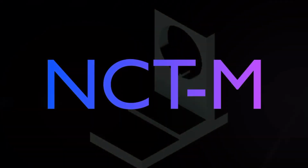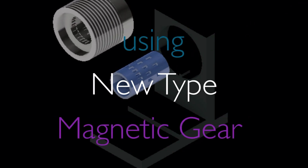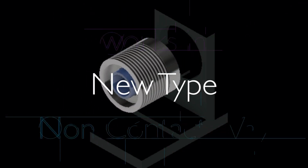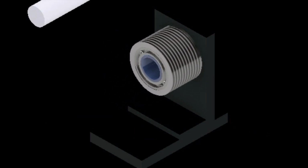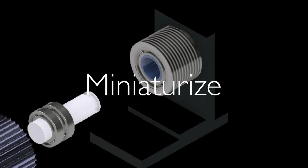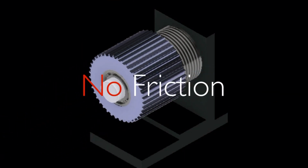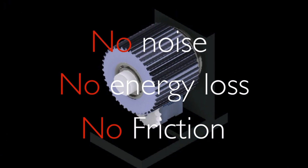This is the final design of NCT-M we invented. It's a completely new system that uses magnetic gear. It's the only system that works in non-contact way. We didn't use any big parts like clutch or pulling levers, so it's the only transmission that can be miniaturized. It's free from friction, energy loss, and also noise of gears.